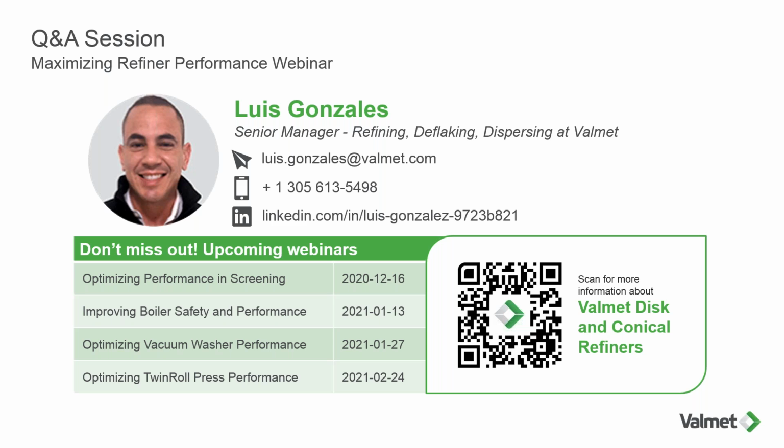So we can do this where we're analyzing the outlet of the refiners twice every 9 minutes and the inlet once. Or we can do it where the more critical ones, like OCC, which is constantly changing inlet freeness, we're analyzing more than, say, a high kappa combination where you're using kraft and OCC mix. We'll analyze the one that's more variable a little bit more than the other one. But the answer is we can put these sample ports pretty much anywhere, and up to 20 of them.